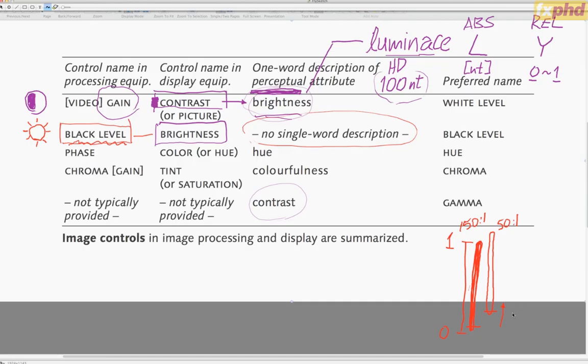Now, it's not necessarily improving it, because if you move the black level control too low, you're able to chop off a whole lot of image data. So you will achieve the maximum contrast ratio of the display, but you do so chopping off image data, losing all kinds of information in the dark tones. So you want to be very, very careful how you set the black level.